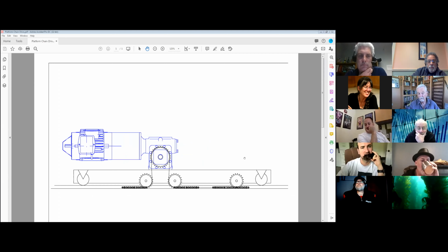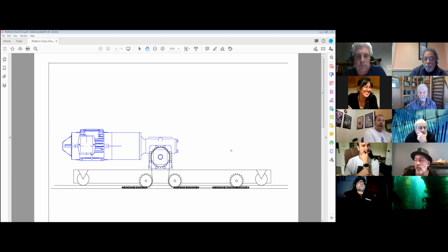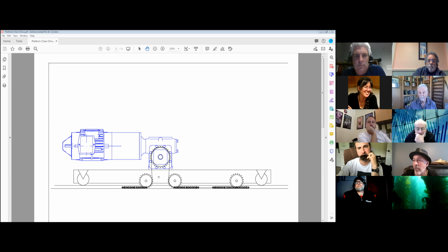Our deck tracks have been 3/4 inches deep, unless we were going to some kind of box track for a special occasion. So basically what this guy here does is the motor crawls along that chain, it picks it up, moves it back and forth, but the chain itself stays stationary, so the wagon moves back and forth. You can do the same thing with wire rope in a 3-groove sheave, but there's more involved to it to get it to tension up and so on.